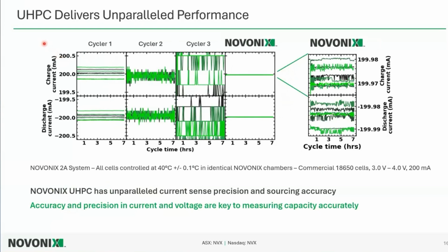So in this plot, I'm showing multiple different cyclers, the same ones that were shown in that CE diagram, showing the spread of all these different cyclers. And you can see there's a big difference between things like cycler 1, which has fairly good resolution or precision, but poor accuracy. It's not accurately hitting the set point that we're trying to apply to the cell.